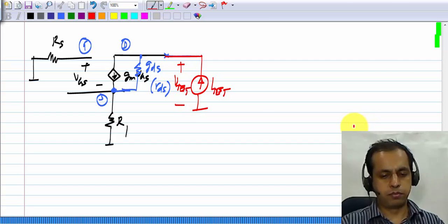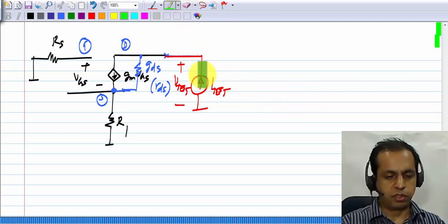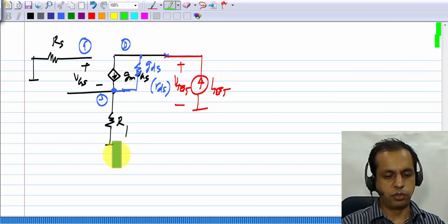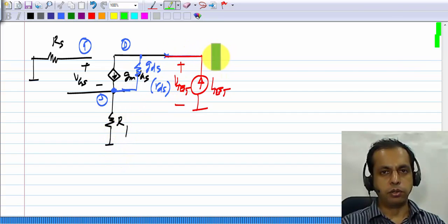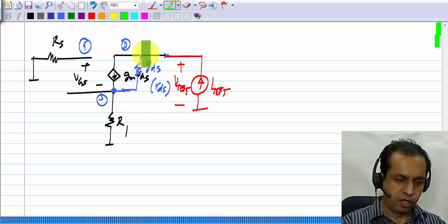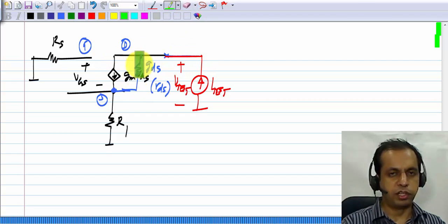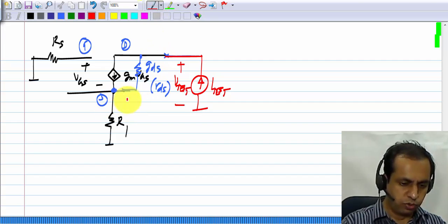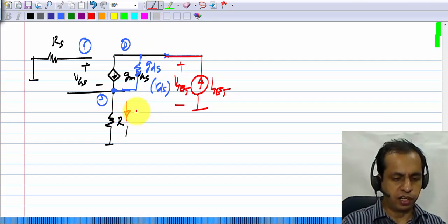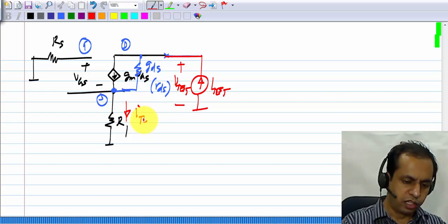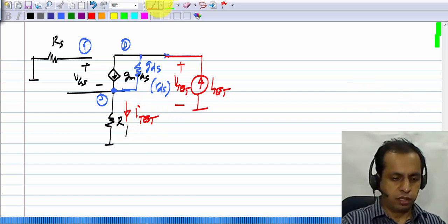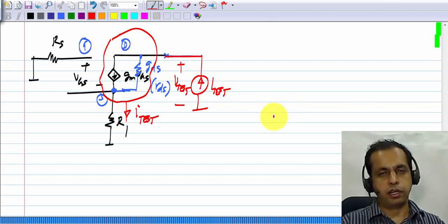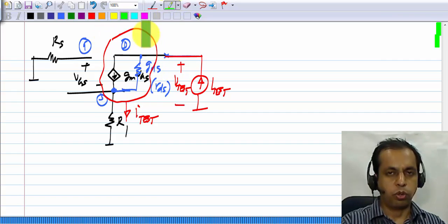Okay, now the easy thing about using a current source is that when you have a number of series paths, the same current flows through all of them, and that can lead to some simplification. Okay. And we don't know how much current is flowing here and how much current is flowing there, but whatever goes into this has to come out here. So it should be very easy to see that the current here is simply equal to Itest. Again, you can imagine that by writing down Kirchhoff's current law around that whole circuit.